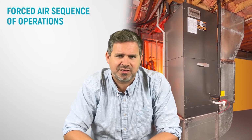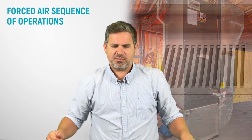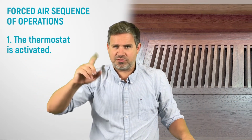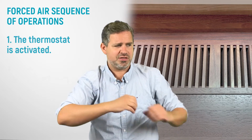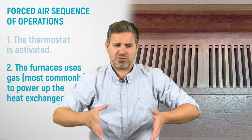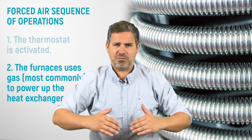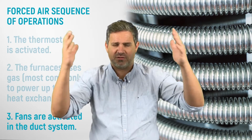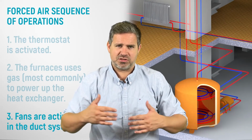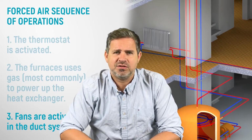Another common thing that people ask us is what is the sequence of operations? What's going on with the forced air system? As I mentioned, the cold air is coming in. The first thing that happens, you turn your thermostat up. As soon as you turn your thermostat up, or as soon as there's a call for heat at your thermostat, poof, the gas comes on inside your forced air system. It's going into the heat exchanger that we talked about before, and then that starts to heat up. On the old school ones, it had a temperature probe, and once it got to a certain temperature, then boom, the fan will kick on. So the temperature and the fan are related to each other. With more modern furnaces, it's more just on a timer, 60 seconds, 90 seconds, stuff like that. So that's your basics of forced air heating.